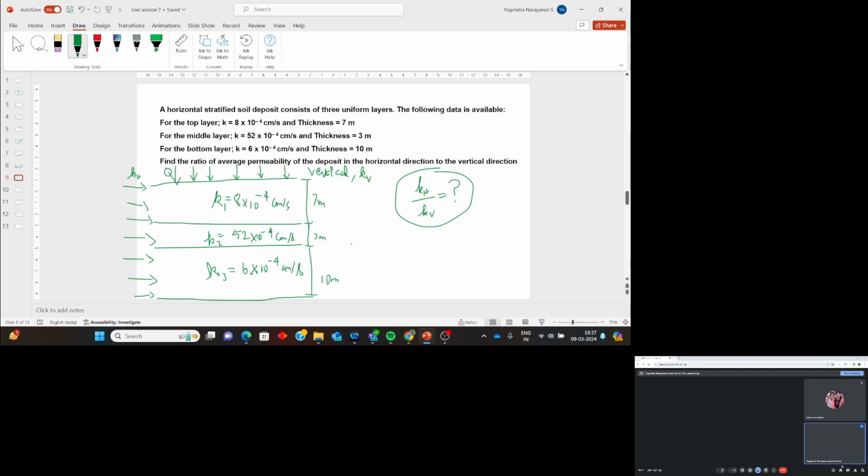1.7666. Okay. So how did you calculate? KH is K1 H1 plus K2 H2 plus K3 H3 by sigma H, and KV is sigma H by H1 by K1 plus H2 by K2 plus H3 by K3.